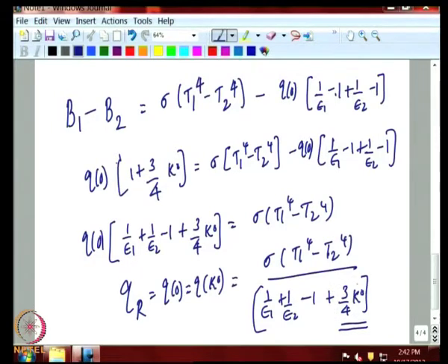So, the gas radiation becomes important only if the two walls are black, and so this becomes 1, and this quantity, let us say, is as high as 10 or so. Otherwise, the gas between two parallel plates is not important if the emissivity of the two walls is very, very small.